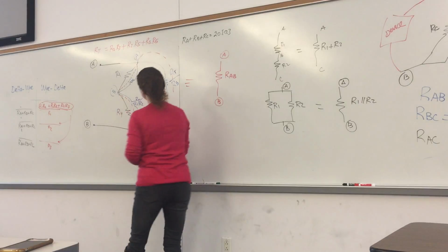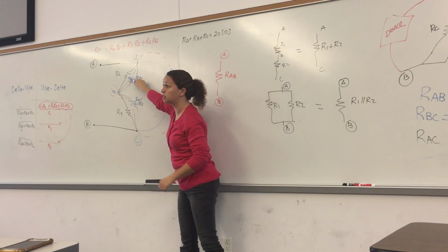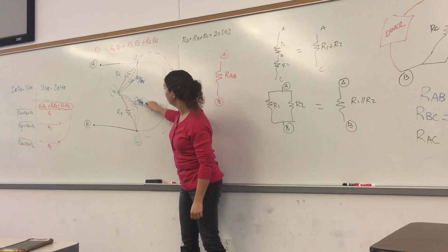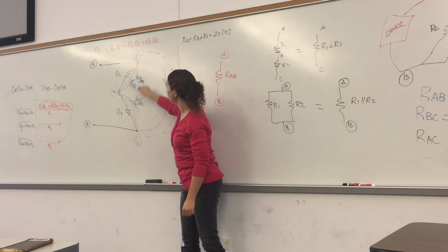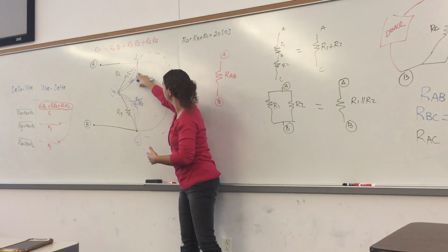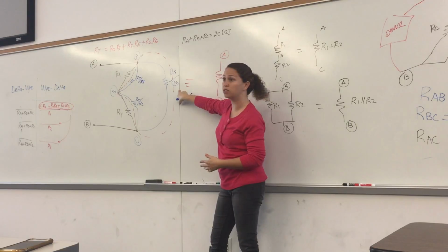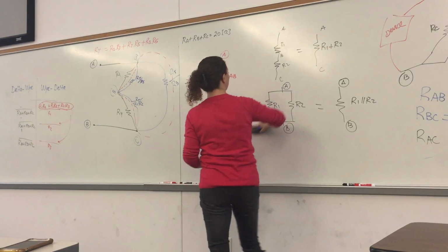And let's see if this is going to make life easier for me. It will, right? Because now this resistor is in parallel with R1. This one is in parallel with R4. The parallel combinations are in series with each other. So I add those, which is in parallel with RT over R3, right? So I can come down to this. So let's write this down.